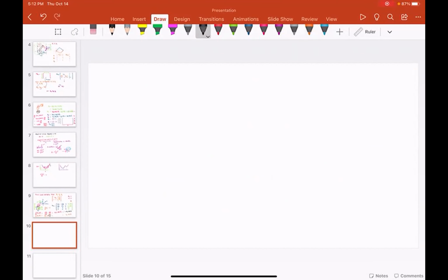I want to write this equation something like this: Px dot, Py dot, Pz dot, the vector on the left hand side, is equal to one matrix. And it is super duper important that this matrix doesn't have to be square. This matrix can be a rectangular matrix multiplied by the joint variables. Are you with me so far? Multiplied by the joint variables. I'm going to write this down something like this.